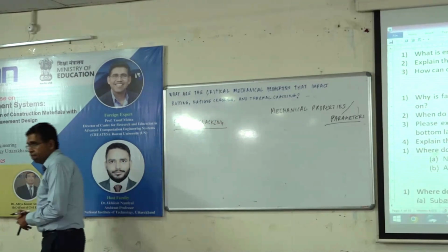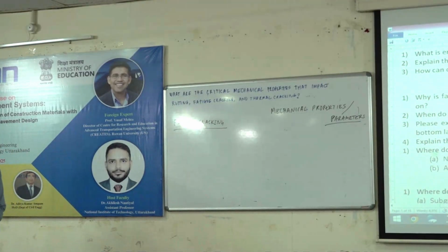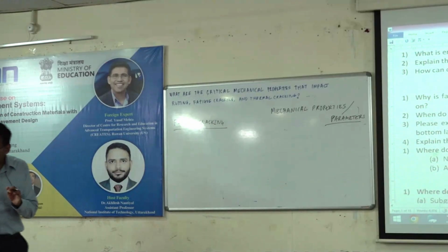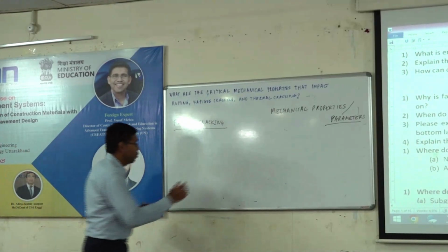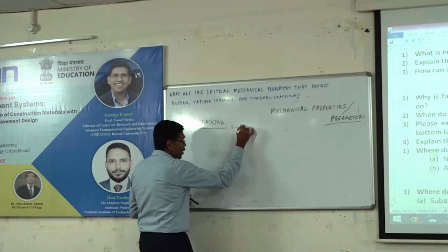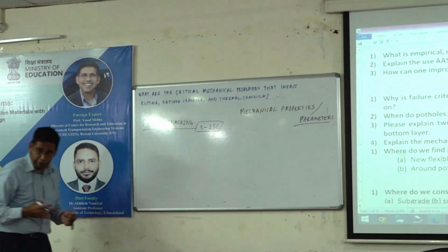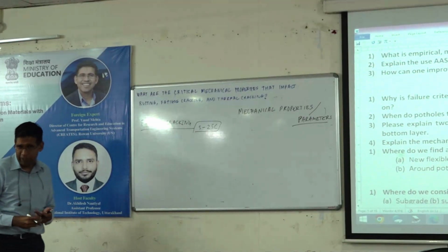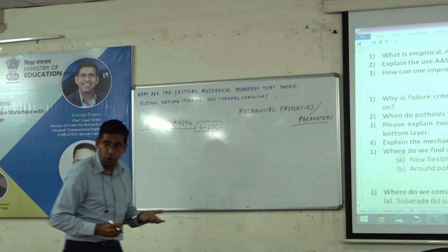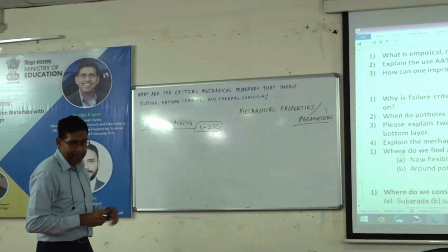When does this happen? Which range? Yeah, so not very cold, not very hot as well, right? So around, let's say, 5 to 25 Celsius, give or take, approximate. So it is not flowing, it is not very hot. Around this range is fair enough, right? It doesn't get too hot. So fatigue cracking happens there.